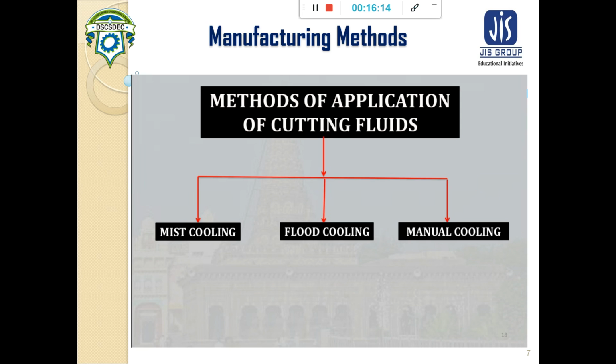Second is flood cooling. Flood cooling is a way where the cutting fluid is applied directly at the chip-tool interface in the form of a flood, and the cooling operation takes place. Next is manual cooling, the method of applying the cutting fluid at the chip-tool interface. These cooling applications are very important.